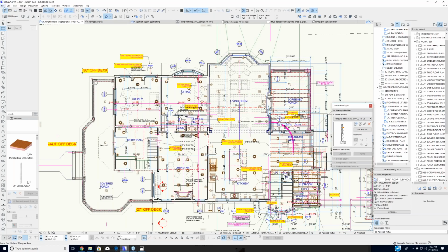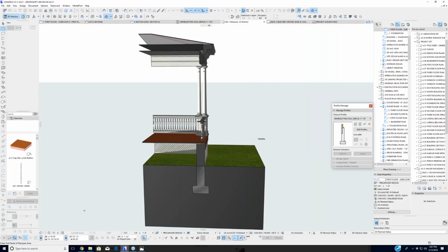What was that, Eric? Go to what? Under the file menu. Yep. Publish BIMX hypermodel is available there. So I guess that instead of save as, it's been moved to there. Oh, you're right. So let me just do that real quick, just so that's clear. If I wanted to send these porch posts as a BIMX file, I would say file, publish BIMX hypermodel, and then it's going to publish just this.